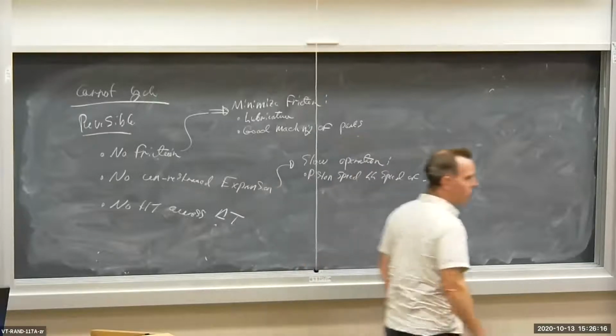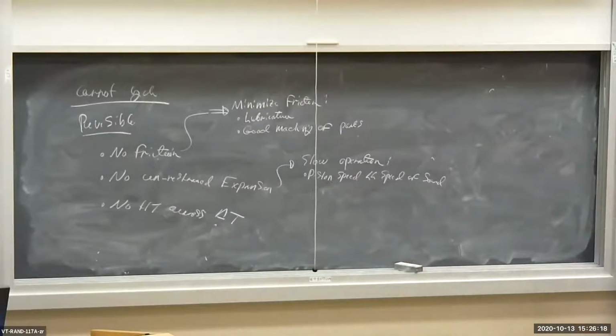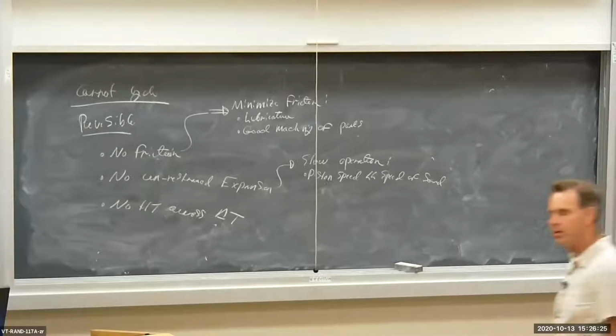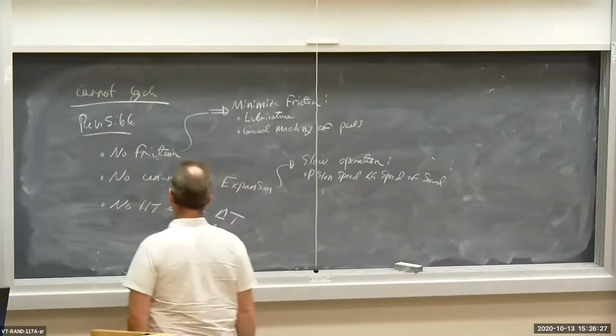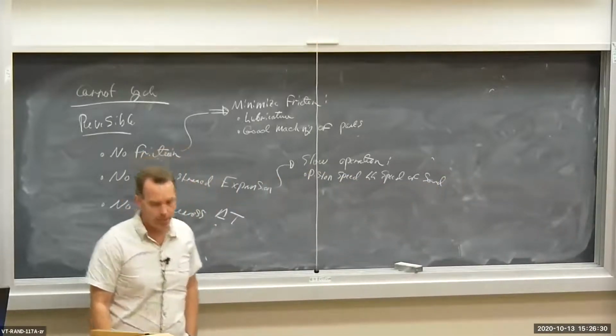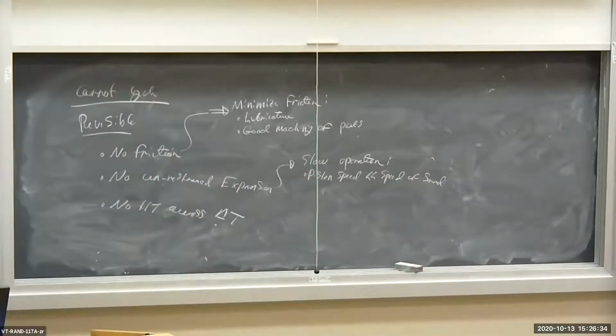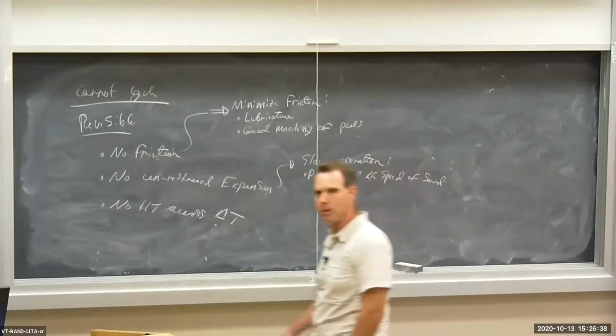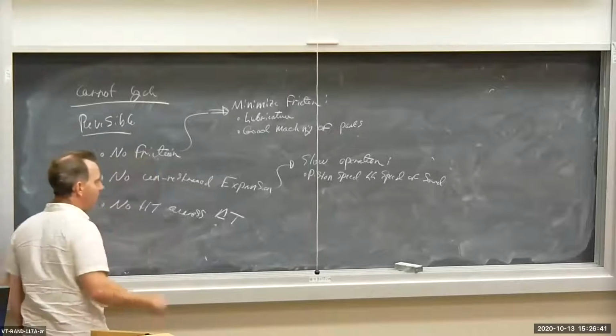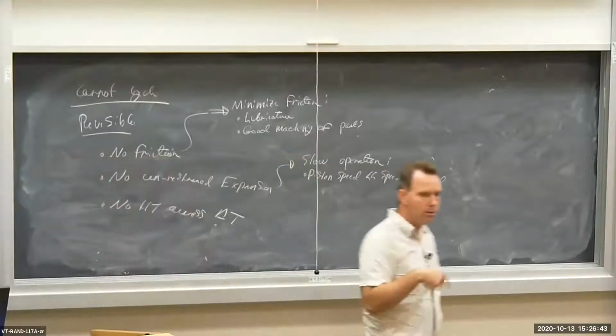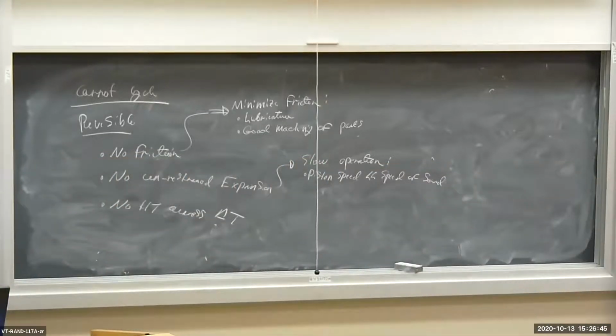Speed of sound is the speed at which a pressure wave propagates through a gas. A gas responds due to the movement of a surface through a pressure wave. So if the pressure wave can't keep up with the piston, you're going to get some kind of unrestrained expansion. So piston speed, much, much less than the speed of sound. That's a way we could have slow turning piston cylinder devices or engines, and that would minimize the presence of unrestrained expansion.